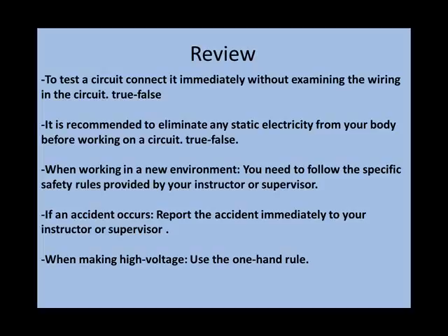And when you have to make high voltage readings of current or voltage, you always need to use the one-hand rule, using one hand only, not both hands. That way you'll be safeguarded, and if something happens, electrical hazard, electrical shock, you will be likely protected by not using both of the hands.